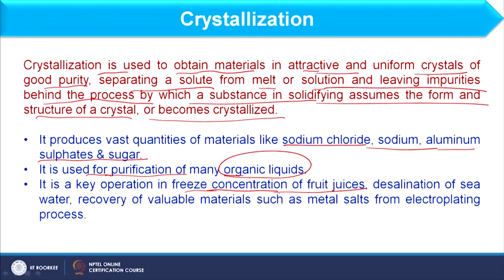It is used for freeze concentration of fruit juice and desalination of sea water. As I have told you, it is used to prepare sodium chloride, and we can also consider it to remove the impurity and generate drinkable water from sea water. So, it is also part of crystallization, but mainly it is not used to prepare drinkable water. It is basically used to prepare the solid which we consider as sodium chloride.